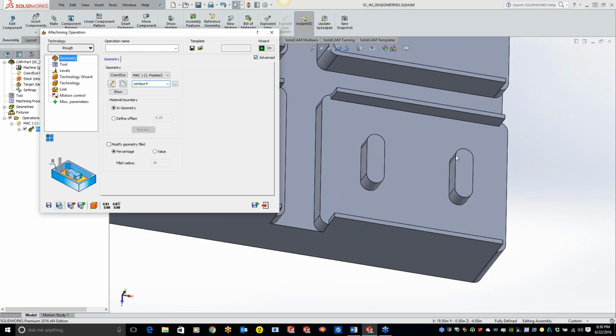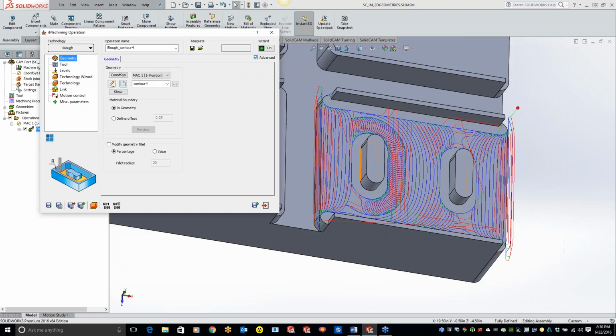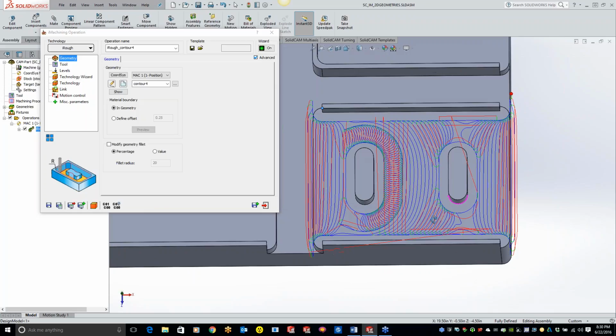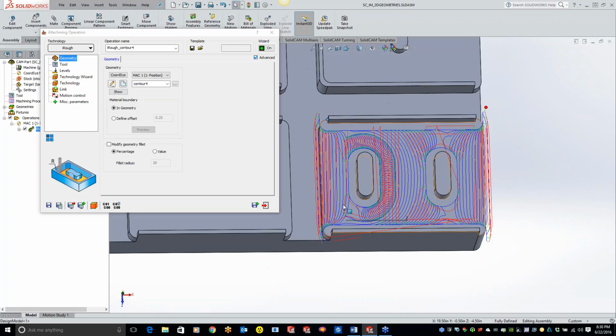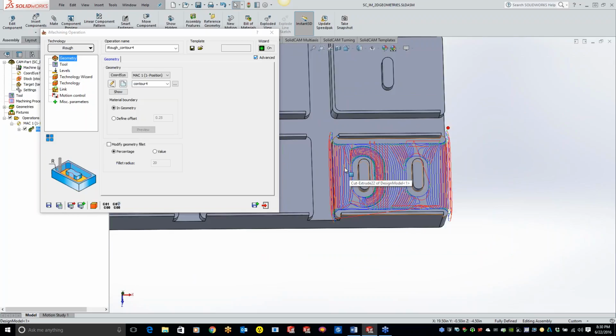And it's going to treat it as two open sides with two islands. So real nice feature for you guys. And I know chaining gets to be a little bit confusing on doing pockets, but that's why I try to do as many different strategies for you guys. So we have two open sides right here with two center islands and two walls.